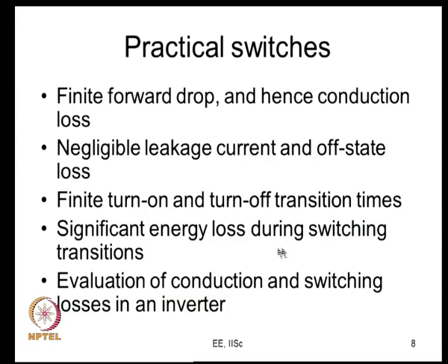Similarly, when the device is turning off, it takes finite amount of time. So, during turning off, what do you expect? You expect the current to fall and then the voltage to rise. Before the current has fallen, the voltage rises. So, there is significant amount of both V across the device and current through the device during such transition. So, that leads to certain amount of power dissipation, and there is an energy loss over the switching interval. So, you call that as switching energy loss. So, there is a significant amount of energy that is lost during turn on and turn off.